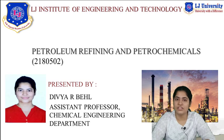See, distillation characteristics is one of the major important parts which is done as a part of crude assay analysis. Crude assay analysis is nothing but evaluation of certain physical properties. Now, in refinery, distillation is the major separation process. So you need to know the boiling range, that is from top product to the bottom product, the boiling range in which you will get various fractions. So crude assay analysis has certain characteristics.